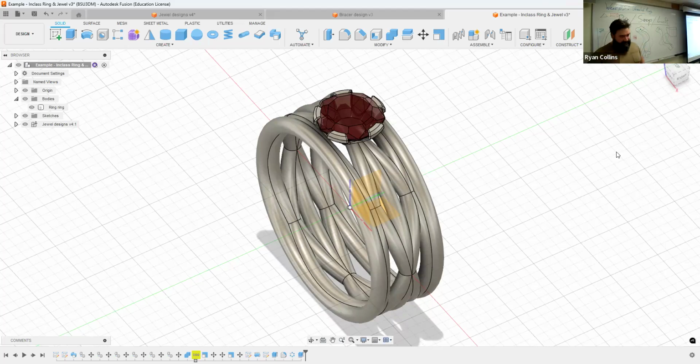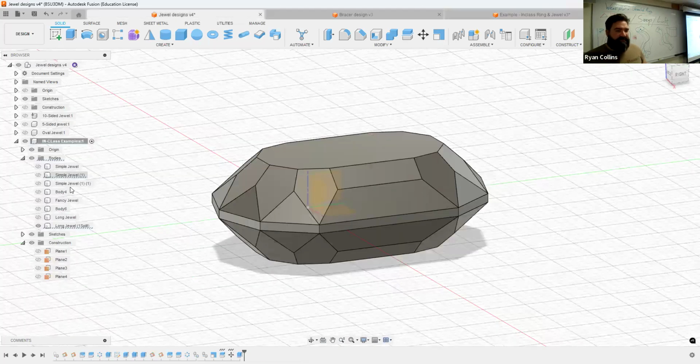Just remember, and I'll write this in the notes, make your jewel polygon in even increments. So it could be 10, 12, 14, 16, 18, 20. Anything more than that, you're probably getting really detailed, but whatever. And when you set the number of faces, either do it in increments of half the number of faces or as many faces as the polygon. Half the number of faces, you get a slightly simpler jewel. As many faces, you get a more complex one.